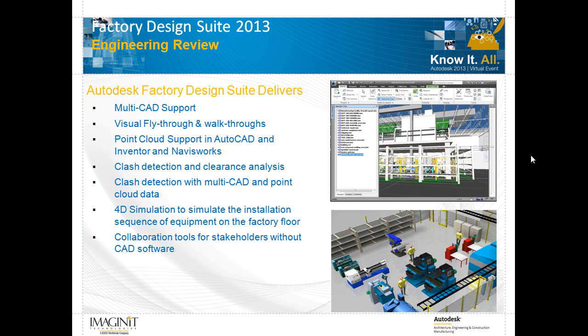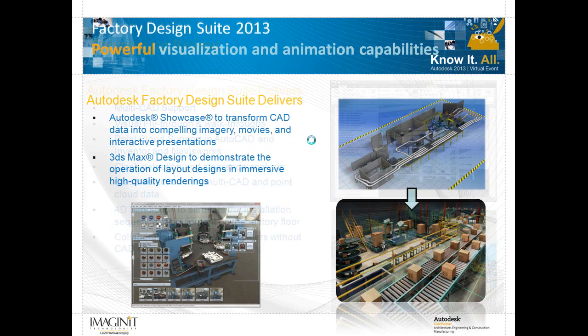And then we can walk through it, fly through it. We have redline markups and measuring tools that we can analyze and publish the things that we find to the team members. It is also a fantastic place for us to find interferences. We can also simulate the construction cycle inside of Navisworks. So at any point in time during the construction phase, I could pause, we call it the timeliner, and we can actually walk around and explore what the facility would look like at a particular day in the construction cycle.